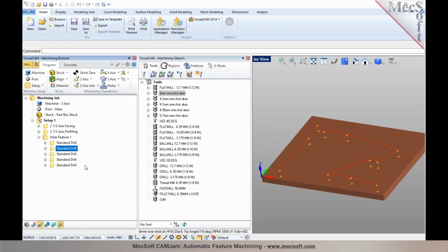So it'll look for a closest diameter tool that's equal to the diameter of the hole feature that you identified. If there's one that's closest to it, it'll automatically grab that one that's equal to the diameter of the hole. If not, it'll pick the next closest one, which is equal to or less than the diameter. So you can see that automatically it selects the tool for it. So this makes your workflow a lot easier and a lot simpler.